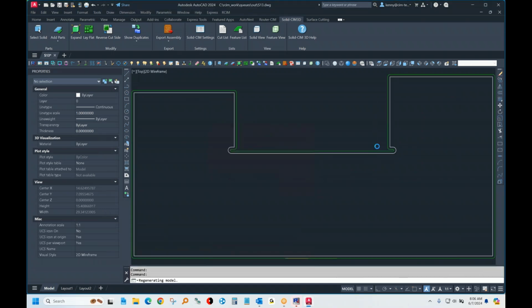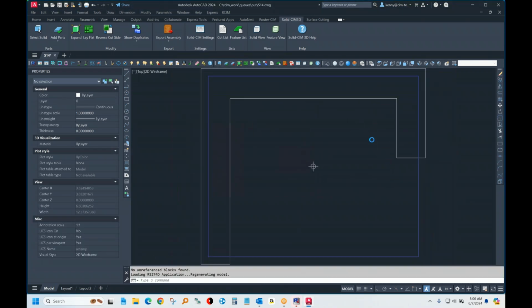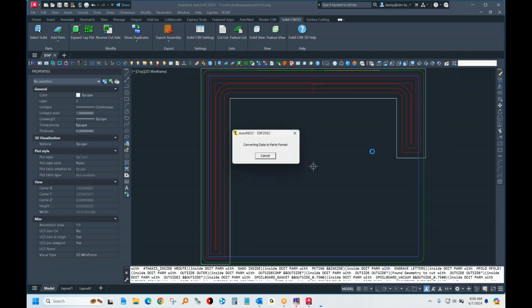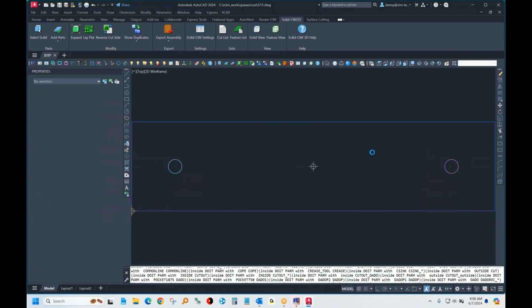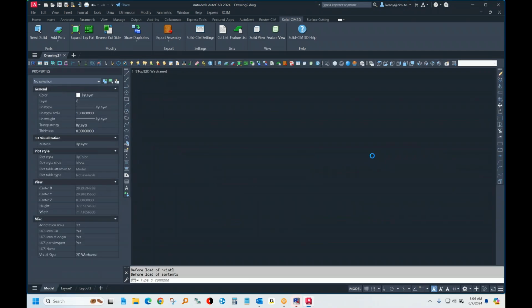Now, you drew these little reliefs in here. You don't need to do that. There's a tool path that can go into a square corner and extend the tool into the corner, so you'll be able to put a square part in there. It's called corner punching.